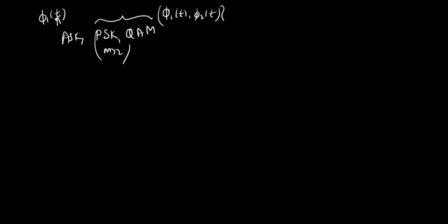So, we started with a very general block diagram, a general bit to constellation mapper, where we said we can have any waveform and any point in any space, any basis. Then we discussed the most popular modulation schemes, ASK, PSK and QAM, and we have seen that for PSK and QAM the basis is 2, and for ASK the basis is 1.